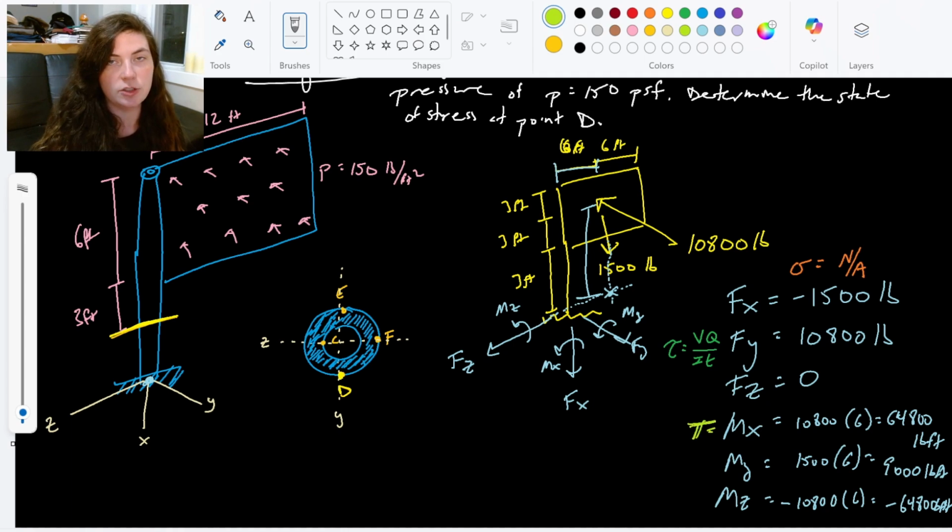A torque and a moment are the same thing for our math and tensor purposes. It's just actually causing motion. So this moment is actually a torque. So this is another shear stress, but this time it's the torque equation. Torque times radius over polar moment of inertia. That's our Mx.